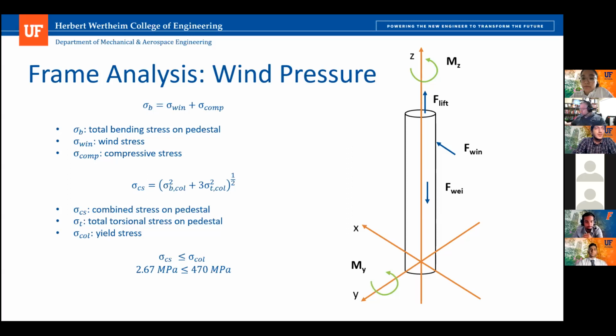Okay. I mean, I will say, yeah, go ahead. So one way we thought about it was that we saw that the mirrors, as you said, are pretty stiff. So at some point, their deflection would result in them cracking or breaking, and that's what we assessed. We assessed what wind loads are going to lead to the system itself or the mirror itself failing, and we didn't include them bending because we assumed that because they're stiff, when they're bent, they're probably going to break. So there's kind of what you're saying in there, but yeah, an exact analysis, we should work on that.